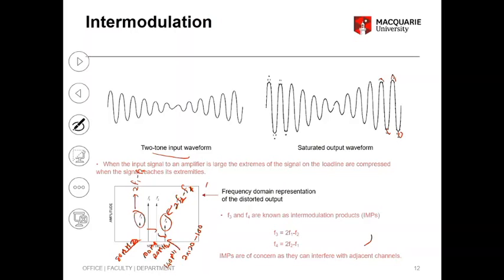So if you have a system that has only one pulse, can it create an intermodulation product? No, it can't, pretty much, because it has only one signal. But in reality, you will have a certain bandwidth. The reason I took two pulse signals is that in reality you will have a bandwidth, which means within that bandwidth you have signals. They could be 1 megahertz apart, but they can themselves actually cause intermodulation, right?